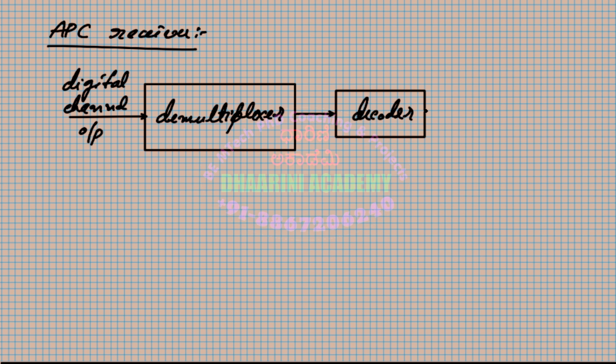The decoder's output is error. From the error, I need to go back to my speech signal, speech samples. That means to this itself, I'm supposed to perform an addition. So this is plus. Previously on the transmitter side, you did a subtraction. Now, in order to come back, I cannot do subtraction. I have to do the addition. So this is also plus. Only that's the difference.